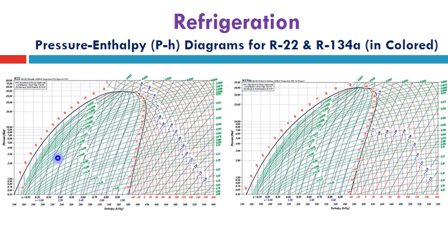It should be clear that the width of R22 between the two saturation lines is larger for the same pressure than that recorded here for R134A, which means that the m dot of refrigerant for R22 for the same cooling load will be less than if using R134A, which for sure will increase the COP of the cycle if using R22 compared with R134A.